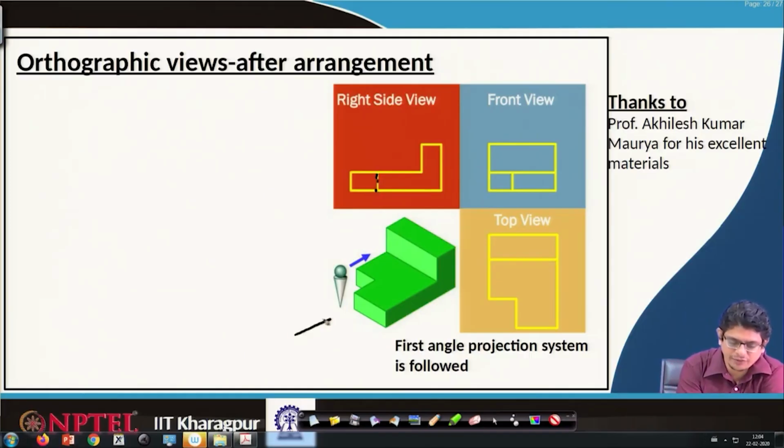If you are looking from the front view, there is a line which is visible, it is a cut, but still visible, and that is the reason we show it by a continuous line. However, in the side view, there is a cut, but we can't view it when we are projecting it. So, to represent that intricate dimension or direction, we show it by a dashed line.